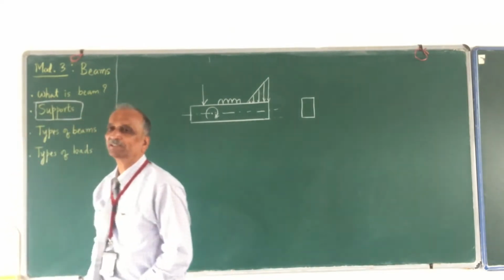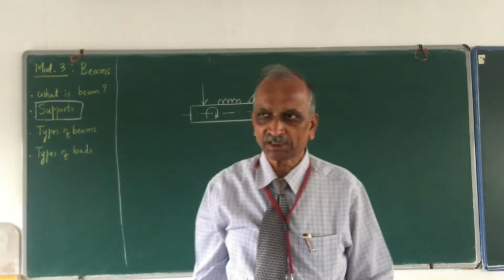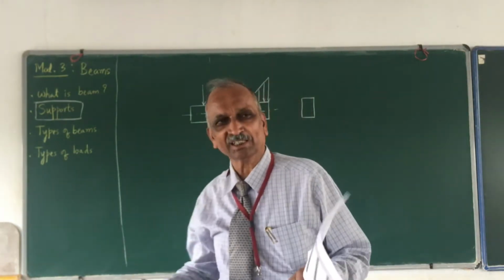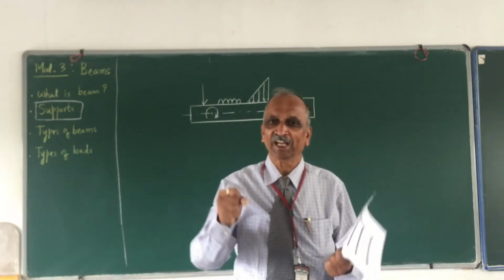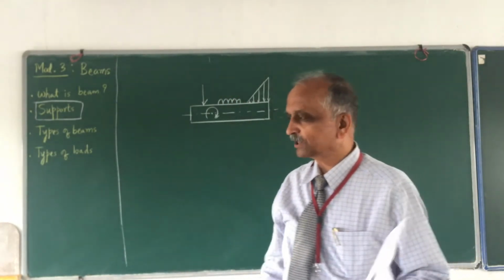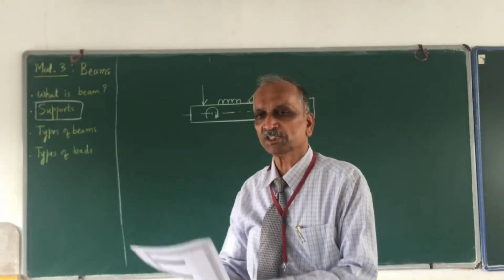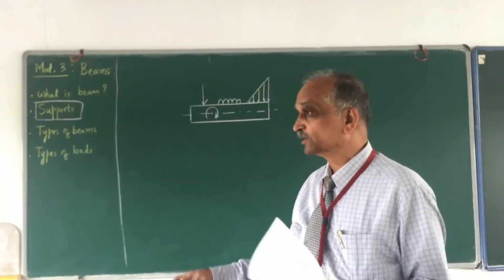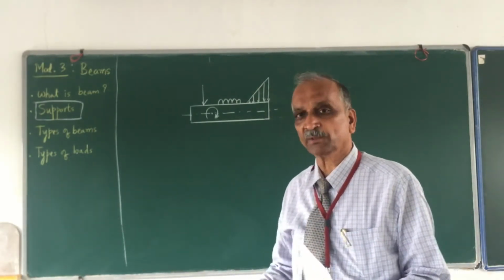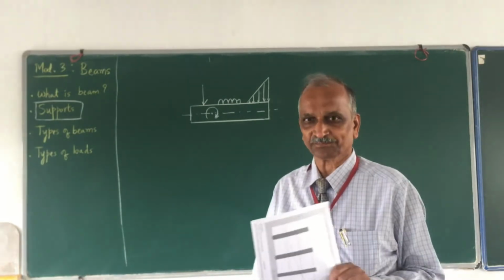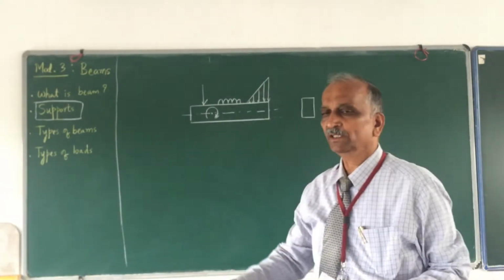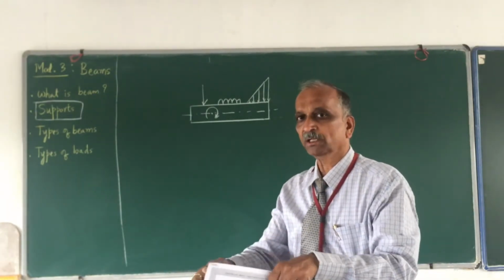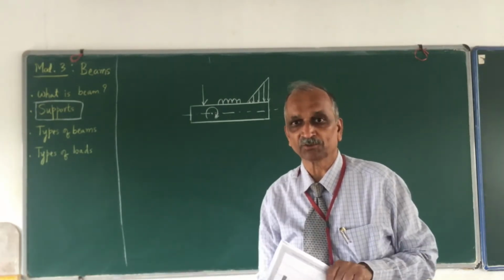Every beam requires supports. Support is nothing but a form of reaction: you are holding it, you are supporting it. There is some other member which is making them remain in that position. That is what we call a support. Support is essential for a beam, but it is not part of the beam. When I isolate the beam, I also have to show what forces are offered by the support on the beam. That also I have to take.